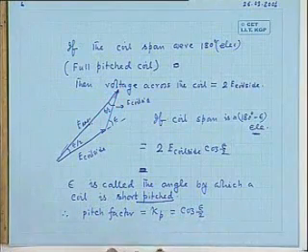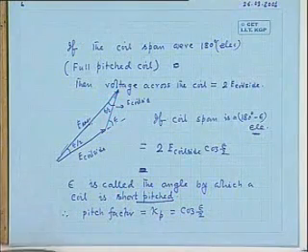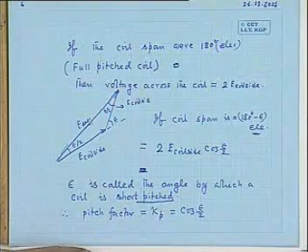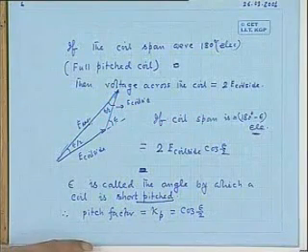Therefore, if a three-phase winding, or a single phase one also, is both distributed and uses short pitched coils instead of full pitched, then the effective number of turns should be multiplied by both Kp and Kd.